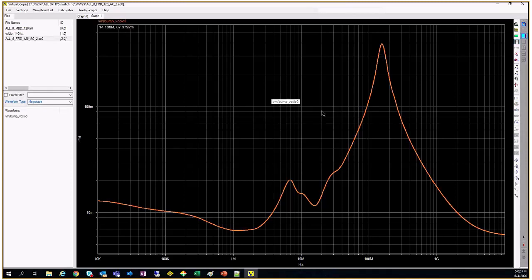So if you see here, you have the impedance versus frequency for a given node, okay, bump location. It is varying from 10 to 1 giga, 2 gigahertz, and it's varying starting as low as like 14, 15, 12 milliohm. Okay, you can notice it over here. You will see the impedance varying over here. It's going up. It's going to about 20 milliohm over here, and then it's reaching the peak which you were saying at around 400, and then it's coming down.